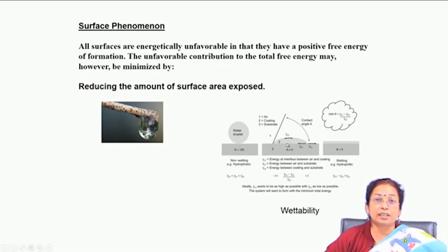When a liquid is poured on the surface of a solid, it may spread or otherwise retain the shape of a sphere. When the contact angle is quite high, you call it a hydrophobic surface. When it is very low, you call it a hydrophilic surface, and the whole thing is driven by the surface energy or interfacial energy.